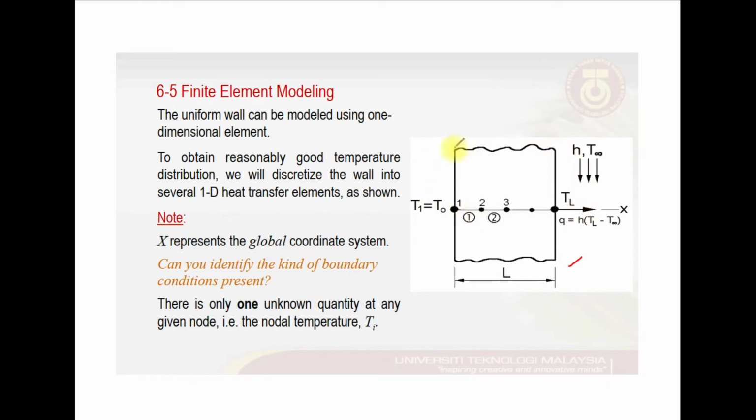So considering this is my plane wall, in 3D it will look something like this, but since we are considering the heat flowing from the left to the right face of this plane wall, we will discretize the wall in the x direction only.